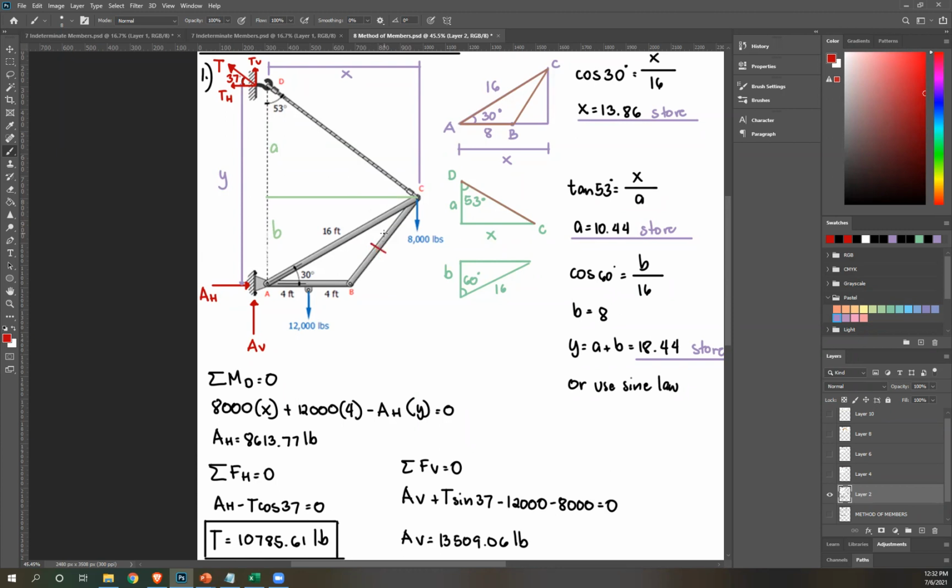Okay. Now if we use method of joints, right, you would typically solve for this and here. Now you can't do that because member AB is a 3-force member, meaning its internal force is not in tension or compression only. So we can't do that. I can't do method of joints. What we can do now is method of sections. Now, as long as you're following the rules for method of sections, you should be able to use it. Now try.